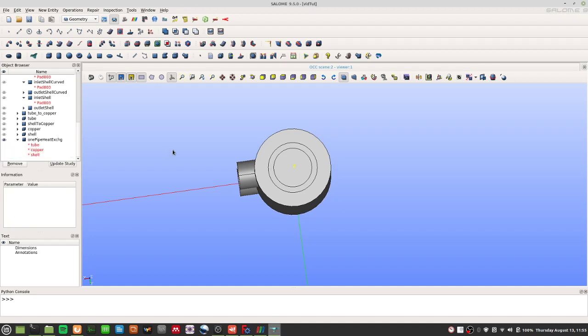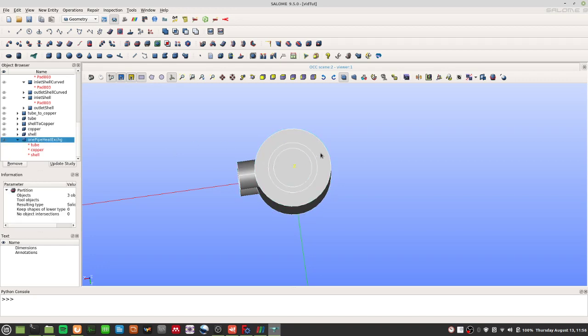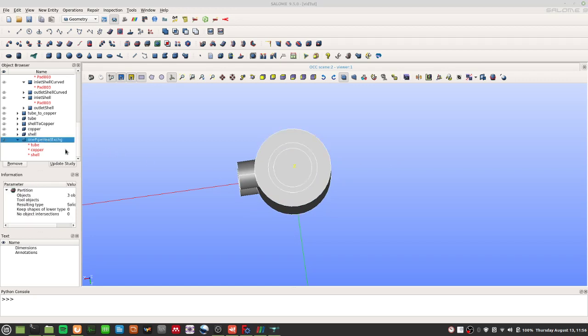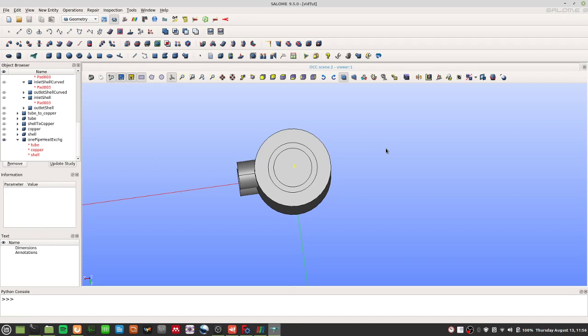Now we'll need to make all the patches and the faces, and of course the individual zones for the individual solids, sub-solids under this one pipe heat exchanger, so that we see what we had in the last video. That has to happen before we start meshing. So we need to split up the regions, and we need to split up the patches.